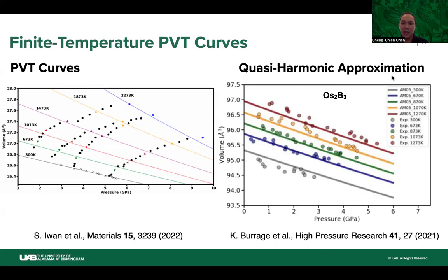However, we know that in these high entropy materials, the structures are stabilized by entropy effects at high temperature. If you look at just the energy terms, quite often these structures are dynamically unstable. This means that their phonon modes have imaginary modes, with negative energies. This means that if you use a quasi-harmonic approximation, it becomes a problem.